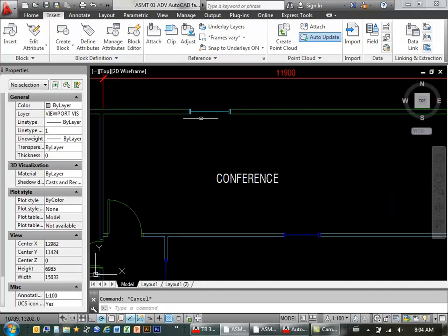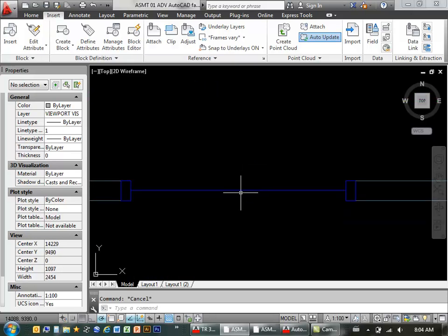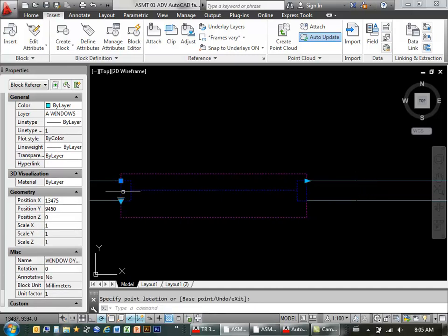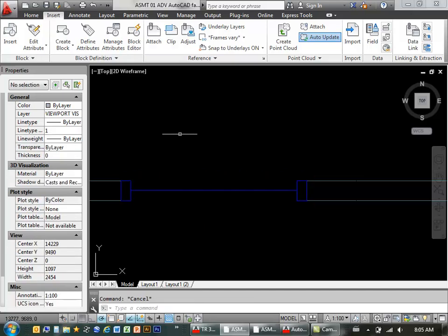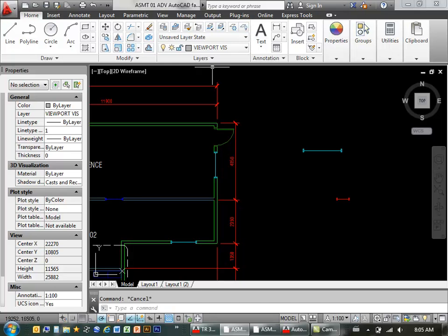So there I have the wider 150 wall, and I just copied that down and inserted it in this sort of interior partition 100 millimeter wall. And it still stretches just like we saw with the door, but it's got the shorter jambs. So I'm going to build that real quick, just over to the side here, and talk about visibility states.